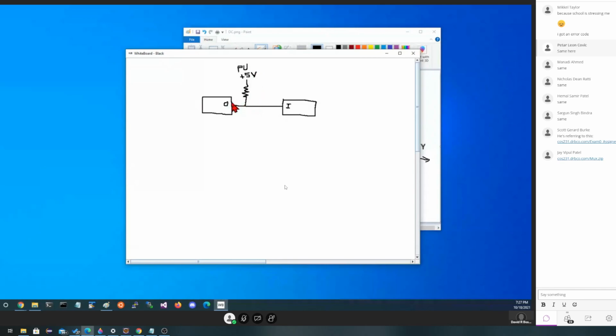So if this guy doesn't connect to anything, meaning he is in that open collector state, meaning he's not connected to the collector because we're trying to produce a 1, that means that this guy is going to get input instead of from him, from and through the pull-up resistor.